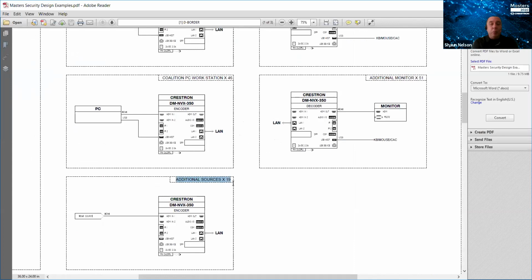And for that reason, we could not do any kind of labeling. You'll notice we actually literally said HDMI source on the flag that's coming into it. That's all they would tell me. That's all I needed to know. I did ask for clarification if it was HDMI 1.4 or HDMI 2, just so I knew from a resolution standpoint what we could and could not support. And I did send them a list of resolutions supported by NVX and let them decide what information they would like to tell me. Because in all honesty, I did not need to know. I just needed to make sure that it could work with our system.